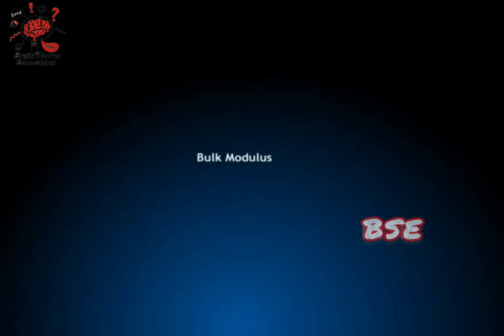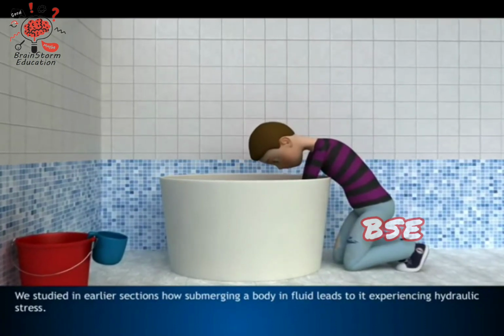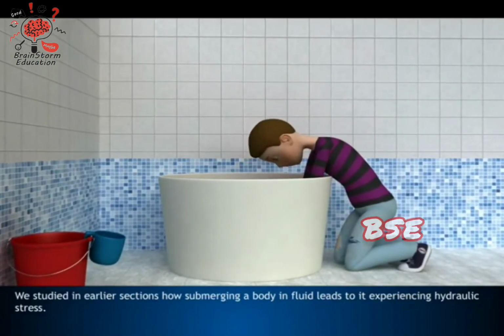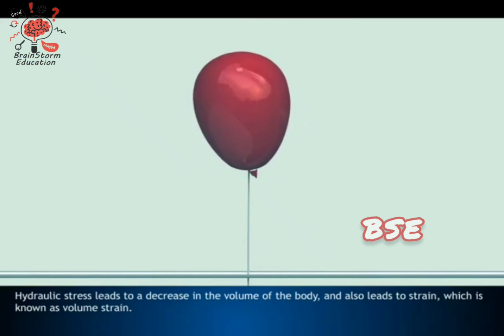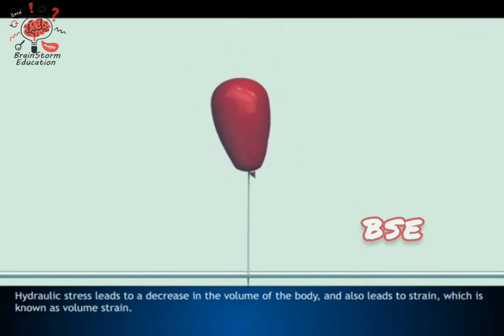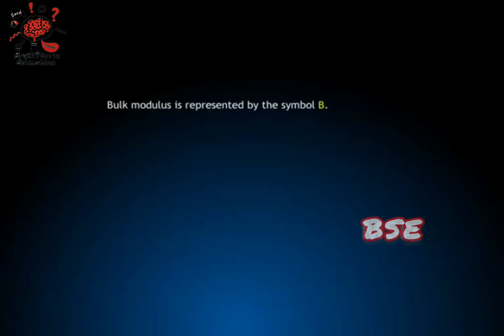Bulk modulus. We studied in earlier sections how submerging a body in fluid leads to it experiencing hydraulic stress. Hydraulic stress leads to a decrease in the volume of the body, and also leads to strain, which is known as volume strain. Bulk modulus is the ratio of hydraulic stress to the corresponding hydraulic strain. Bulk modulus is represented by the symbol B.